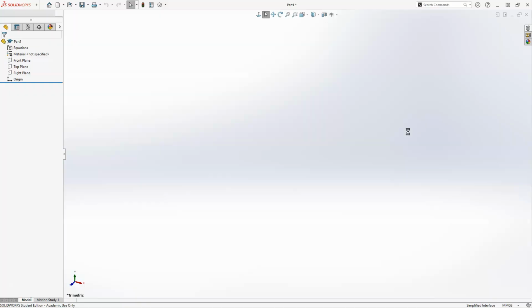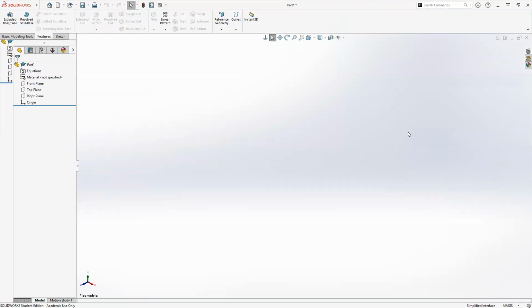But if you're looking at this one, you see it's a cylindrical part. That should automatically tell you that we're going to do something a little bit different. Now, we plan on creating a revolve. Remember that a revolve has to have two components. It has to have a profile now, and I'm saying a profile here in SolidWorks. If we were talking Inventor or AutoCAD, it would have to be a closed profile. But here in SolidWorks, we can get away with a thin feature and use that to revolve. So that's going to be the first thing we're going to need, some kind of profile, and then we're going to need an axis of revolution.